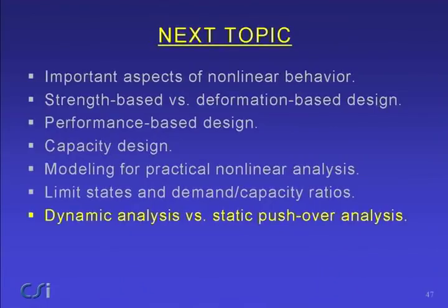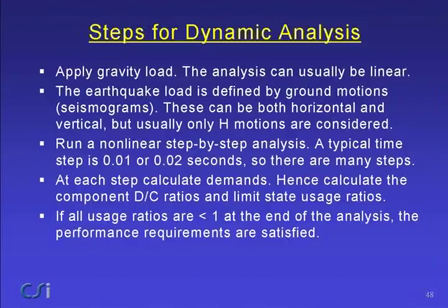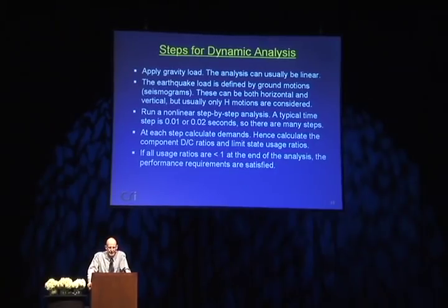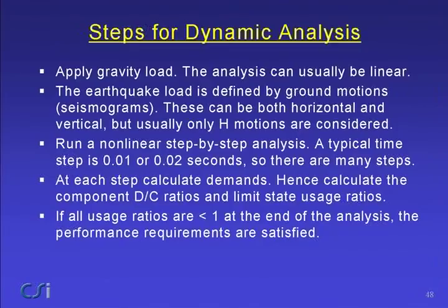Next topic, let's look at dynamic analysis versus static pushover, briefly. Dynamic analysis first, the steps are as follows. Apply the gravity load first. Usually, the analysis can be linear. Not always, but usually. The earthquake load is defined by ground motion, seismograms or accelerograms. Typically, you'll have both horizontal and vertical seismograms. Usually, you'll only consider the horizontal motions. You can consider vertical motions in Perform 3D if you like, but it opens up all sorts of cans of worms, and usually we don't.